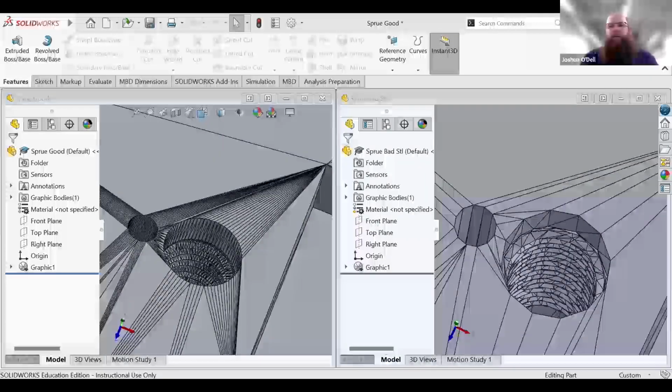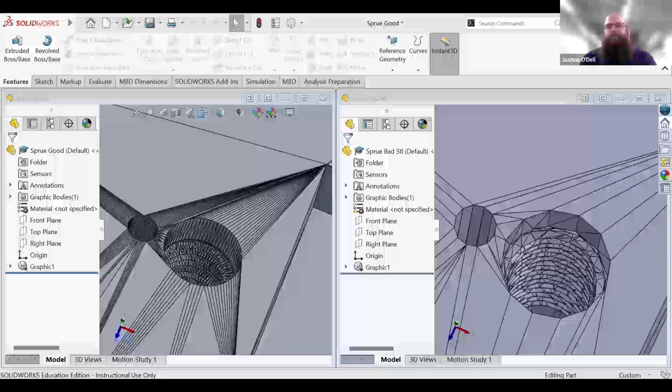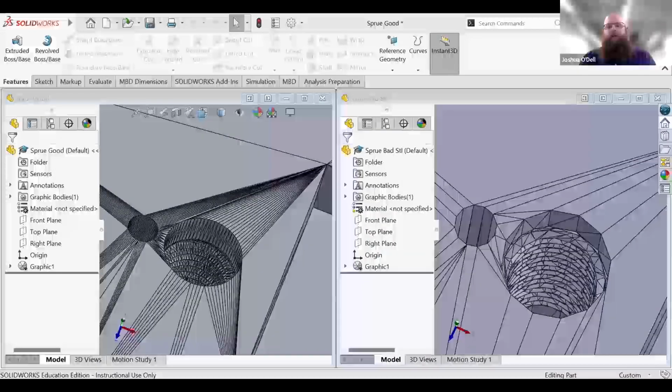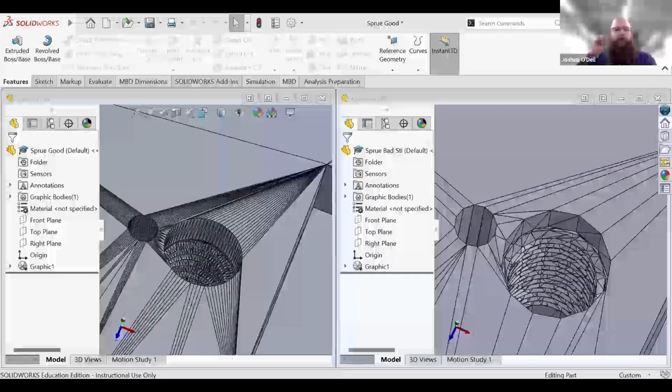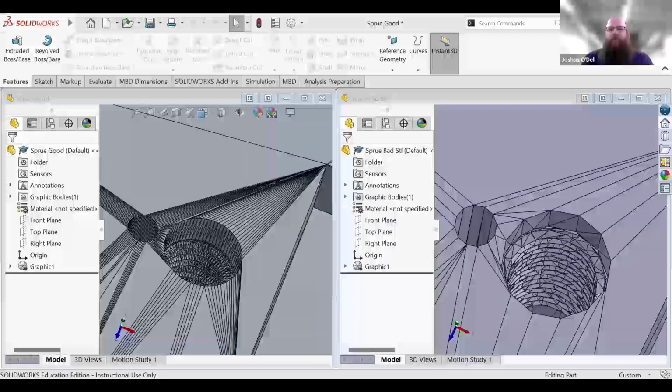Does the quality of the print vary more based on the brand of printer or the price? I'd say, honestly, it's often the price. Usually the more expensive printers will give you more control of how the printer is actually printing. You can refine the qualities of it a little better. I'm not really brand specific. For fuse filament especially, I'm not sure if there's one crowning jewel printer or if they're all run pretty much the same set of G code. It's really going to differ on the extruder part and the nozzle part. And even then, a lot of the nozzles and extruders are becoming more and more homogenized, and they're all using very similar brands on that end of things.